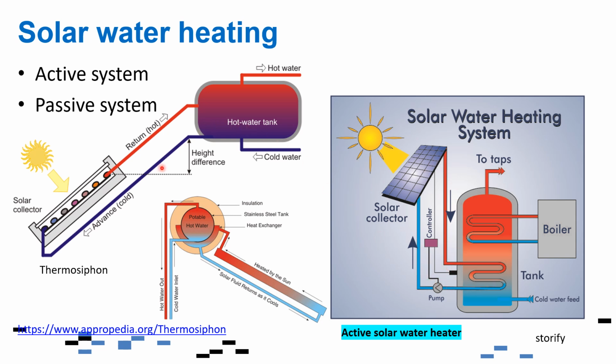In this system, a slower cycle, but less energy intensive. It means it's more economical, but it's only good for a small system. If you have a really big system, then it will be more complicated to work on with natural convection. So the height difference is important so as to prevent the backflow of the water at nighttime, for example, if it's cold already. All right. So this solar water heating system directly uses the solar light or solar radiation into heating up a specific liquid and also for specific uses of heating up the space.